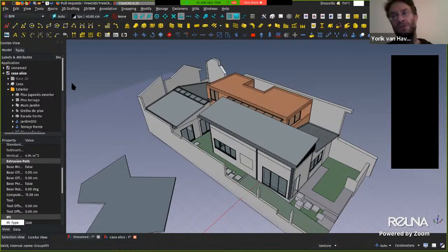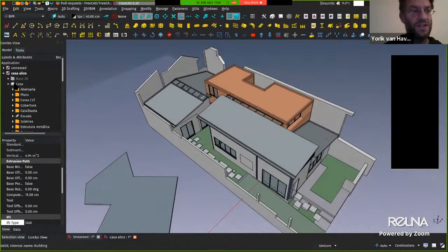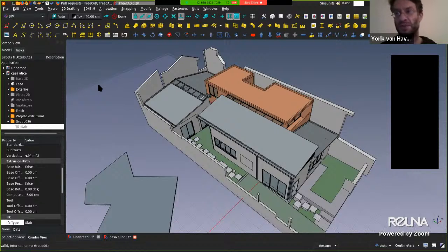That's basically how other BIM applications work mostly. You can do that in FreeCAD as well. We have a building object, a floor object, where you can put your objects the same way as groups. But you're not really forced to use that. And if you don't really need to, for example if you won't export your stuff to other applications, then it's of little use.